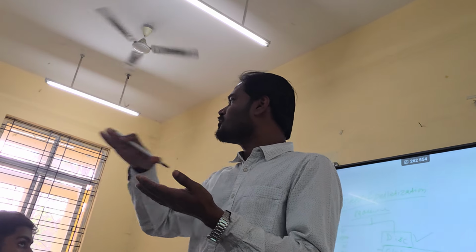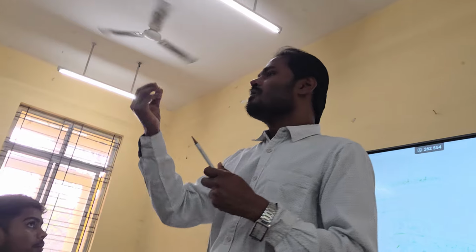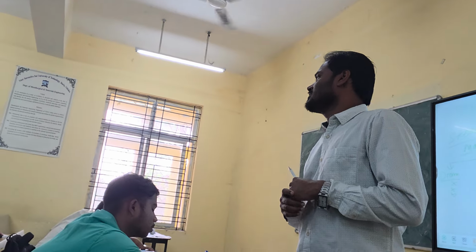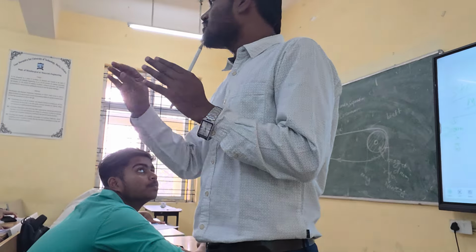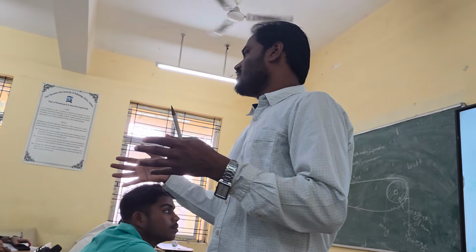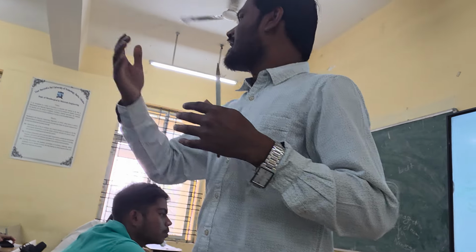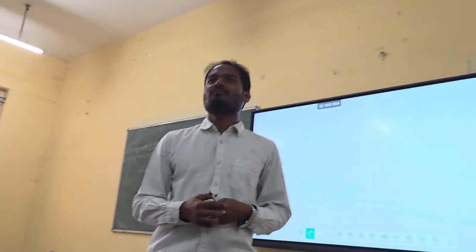If the size of the pellet is very uniform, that is very good. You will get more uniform permeability inside the furnace. Right? You understood? The pellet size will be nearly uniform: 16 mm, 18 mm, 17 mm, for example. But if you use a drum, the size of the pellets will be very different: 10, 20, 15, 18, 17. So that is not good actually.